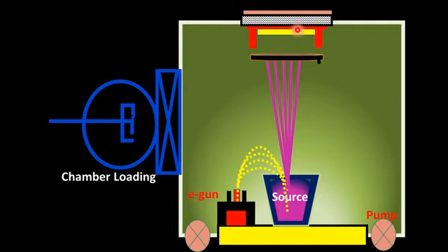The reason for heating the substrate is the uniform deposition of the precursor material. Heating the substrate first causes desorption of any liquid phase impurity present, and secondly it provides uniformity in the deposition of the thin film.